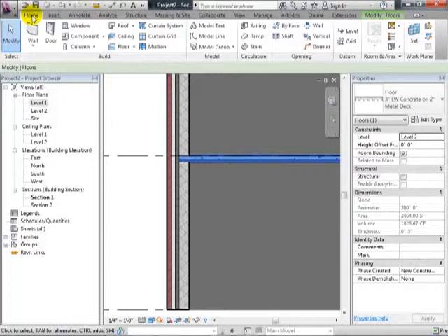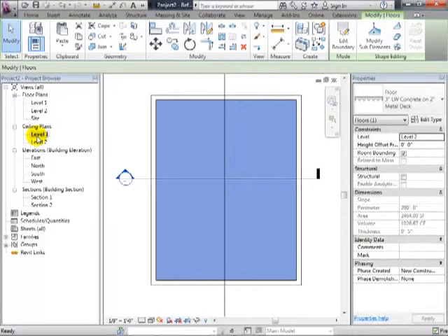But if you want to prevent that, the thing to do is, when you're placing beams, don't place them in floor plan views. If you place them in ceiling plan views and look up instead, you'll do a lot better in terms of actually putting them where they need to be. So let's show you what I mean by that. If you go to, for example, the ceiling plan view, and let's go to the ceiling plan of level 1, it's going to look pretty boring right now, but what we're doing is we're at level 1, cutting at 4 feet, looking up at the ceiling. So what we're seeing is the bottom of floor 2 right now. So when it's time to go through and place a beam, you can go through.